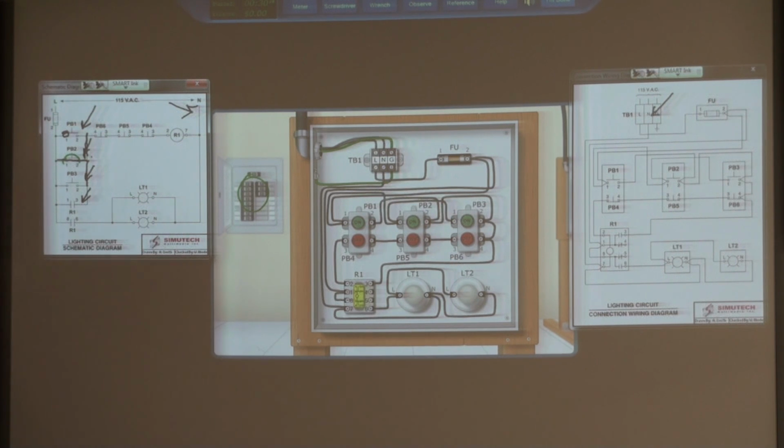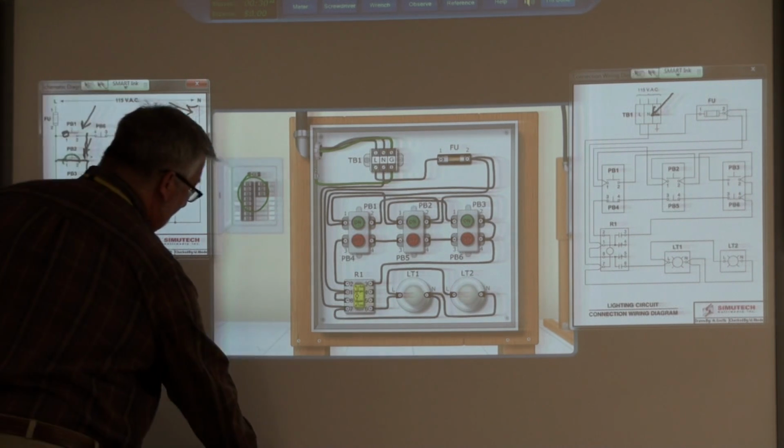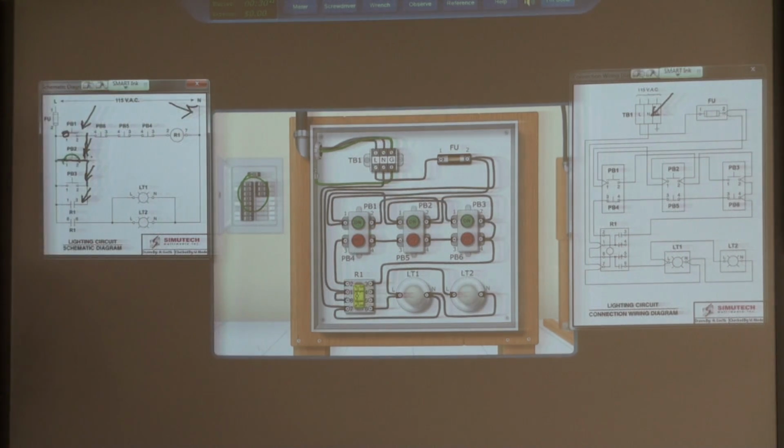So that's where we have to go from volt mode to ohm mode. We're going to shut our power off and change our meter to ohms, or we have to ohm out. I forgot that. Yep. So that's where it gets a little wonky in our minds sometimes, just like a while ago when I tried to say that about that thing not having power. Yes, it does. It's provided by something that's in parallel with it.